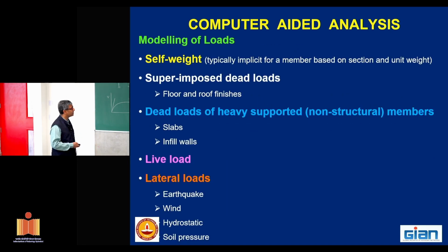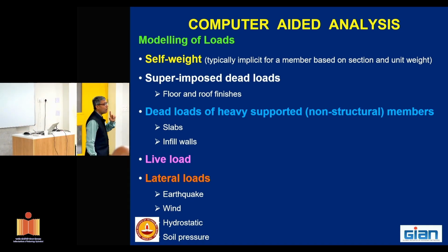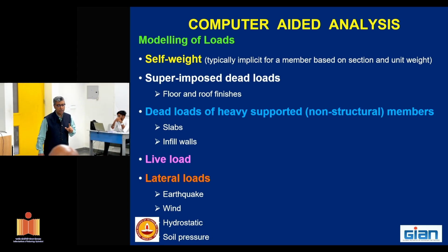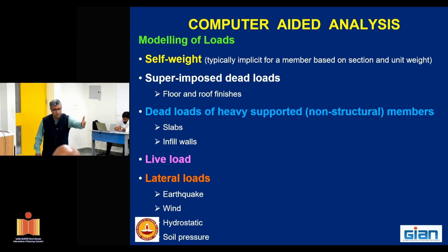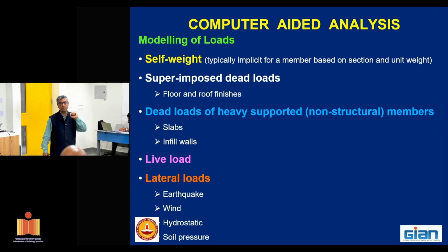What I will do is, see, whenever you are modeling a building, please note it is only as good as your model. What I mean is, you cannot miss out on very heavy loads. If I am having these steps made up of concrete on a flat, I need to include this superimposed dead load.